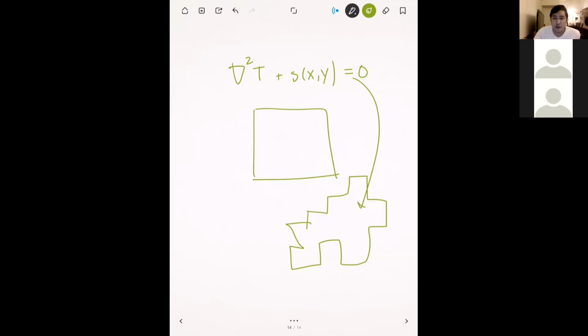And if you satisfy certain conditions for your assumed solution, which the finite element form tends to do, you get something that's not quite exact, but really, really close, especially if you refine your mesh quite a bit. If you have a really refined mesh, then your weak form solution is basically going to be right on top of your exact solution. So you're right, in the cases where you can find an exact solution, that's the preferable way to solve it. But for cases where you can't, this approximate method saves you a ton of work.